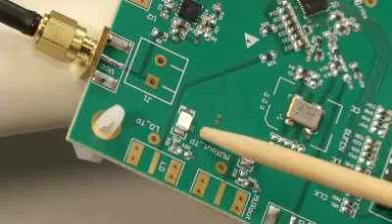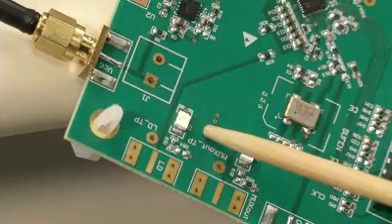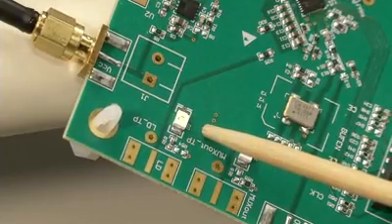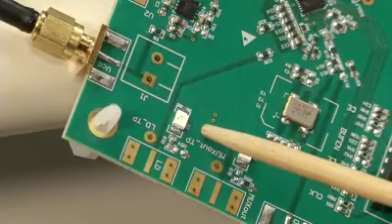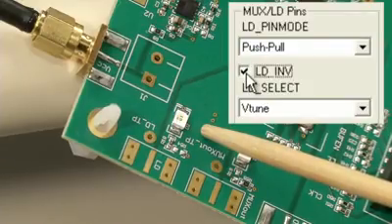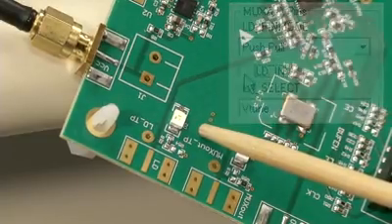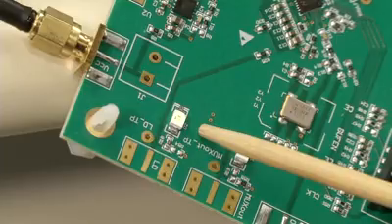For instance, if we look at the green LED light on the board, right now it's set to show the lock detect if the V-tune voltage for the VCO is in the proper range. So high would indicate the device is locked. We can actually invert that to mean low is locked. So by clicking this bit, we can toggle this on or off. So this gives us an indication of programming that would work even if the synthesizer had some other issue or there was invalid reference or whatever it was.